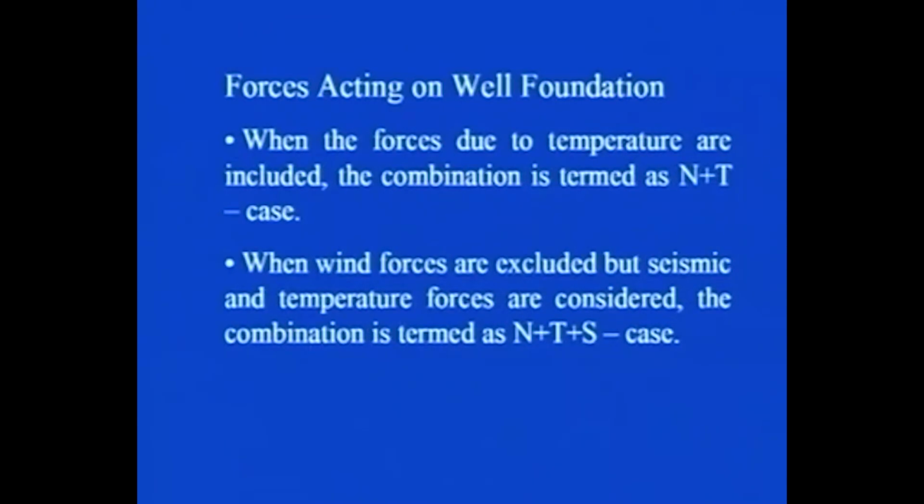When the forces due to temperature are included, then the combination is termed as N plus T case. That means only seismic forces you have neglected, and all the rest of the forces you have taken into account. So, this particular combination is known as N plus T case.